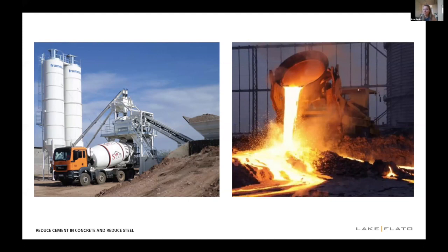And then when it comes to steel, some of the things is of course using recycled steel. Fortunately, this is something that happens in the industry already, which is really great to hear that we can use recycled steel as much as possible. Another interesting way to do this is researching the type of furnace that's being used in the manufacture. So you can look into how clean or dirty that energy used at the facility is in order to help improve that embodied carbon emission. And then of course, there's also steel optimization. People are getting really creative in ways to optimize their building to reduce the material needed, but still have the same structural support.